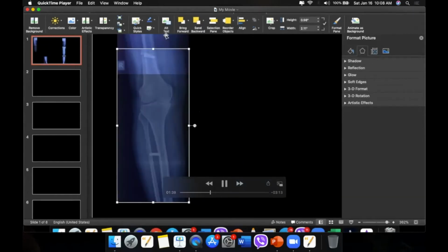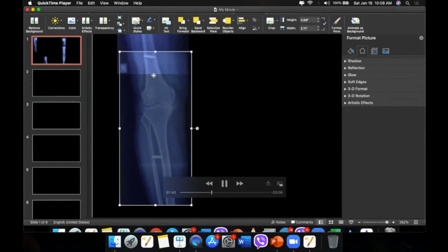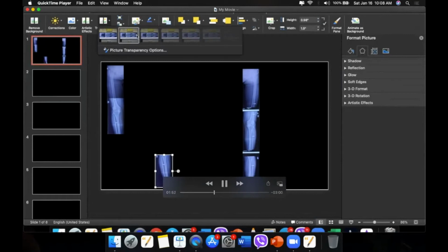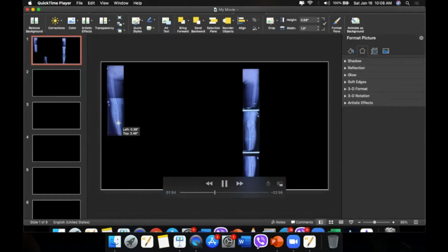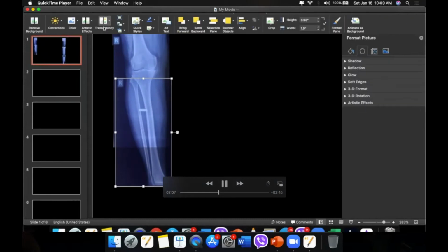Then what we do is we reduce the transparency of the second part and overlap that into the first part so that the markers will perfectly overlap. Then we get back to the original transparency of the second one. Then again, we reduce the transparency of the third one, then overlap that again into the second part.